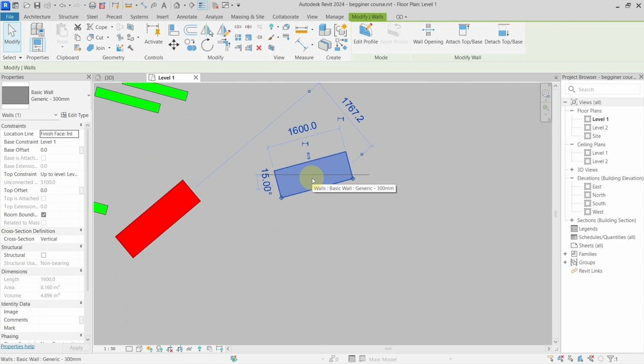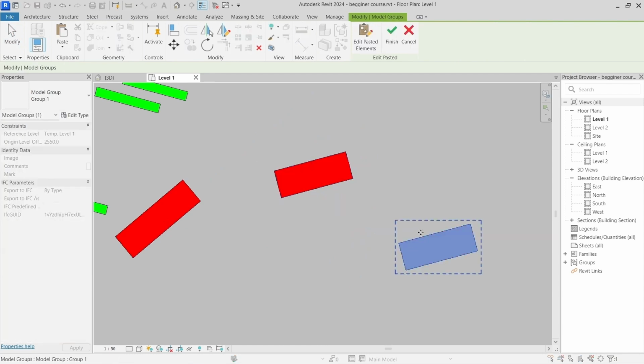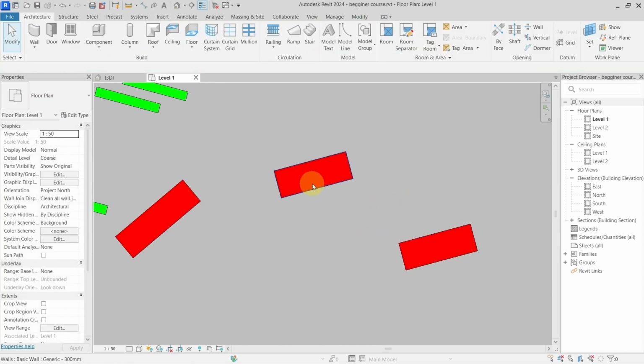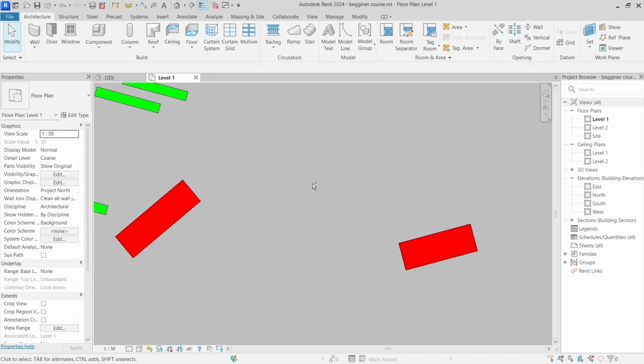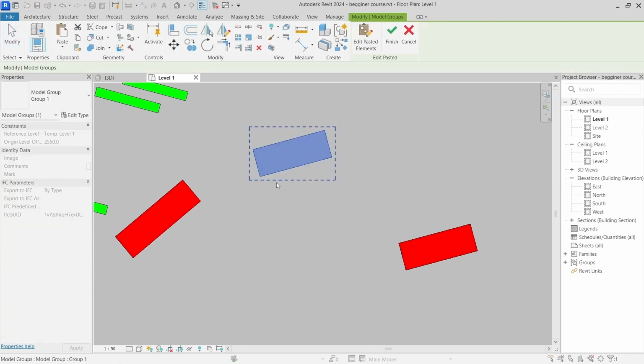If I select this wall and go with Ctrl plus C, I'm copying this to clipboard. The element stays in the file. And now Ctrl V and I can place the element. Whereas if I do the same with the Ctrl plus X, it copied to the clipboard, but it deleted the original element. And now with the Ctrl V, I can place it again.